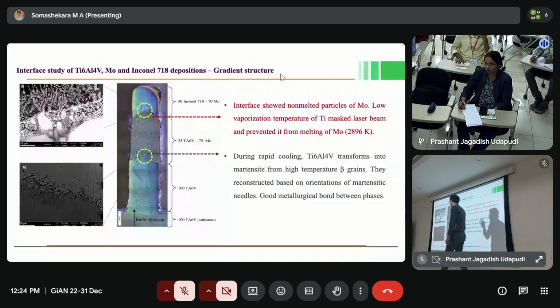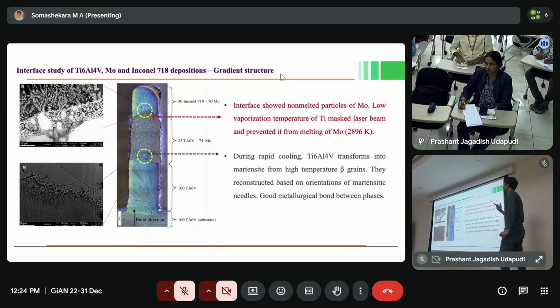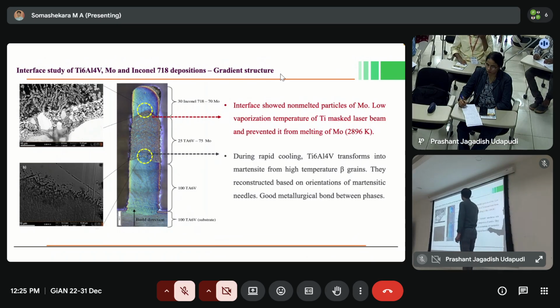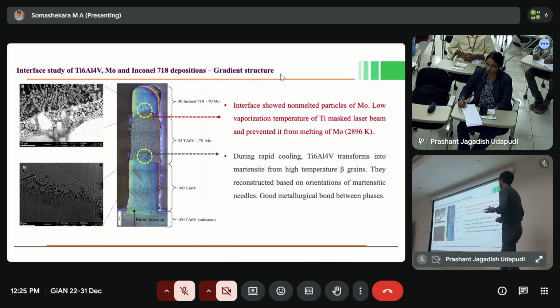Even though I thought that by varying laser power accordingly, you can control what kind of material composition you're trying, still when it comes to the intermediate between the materials or the composition, you will see a lot of issues at the interface. Sometimes you will find cracks, and you can clearly see that the material is changing. The change is because you may have suddenly changed too much.